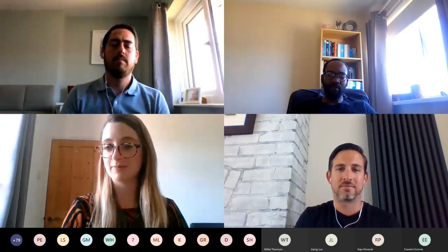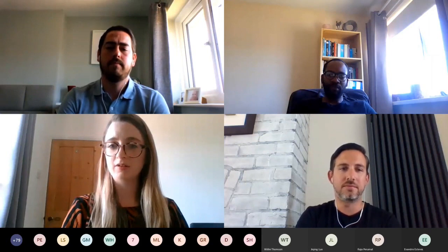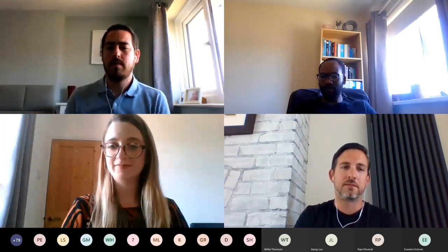EXI is designed for zone 0. If it is zone 0, you shall stop the potential gas migration through the cable to zone 1 or zone 2. So the EXI gland must seal. Would anyone like to comment on that? Sim, do you want to cover that?